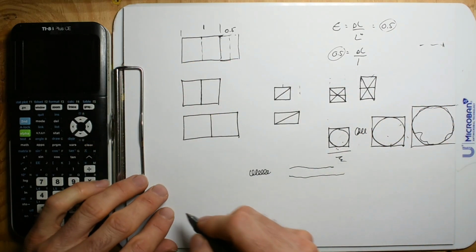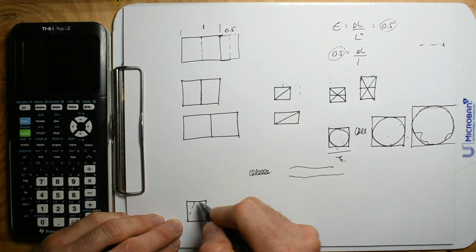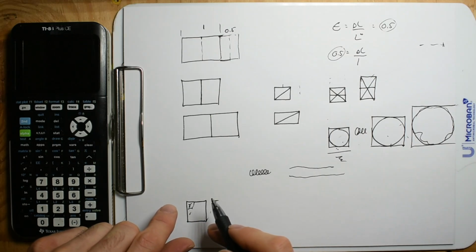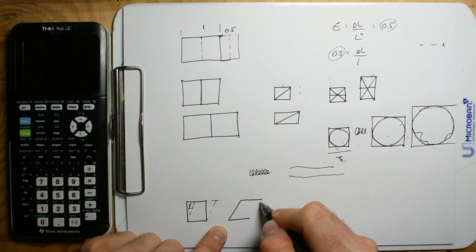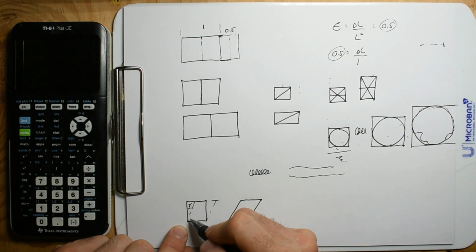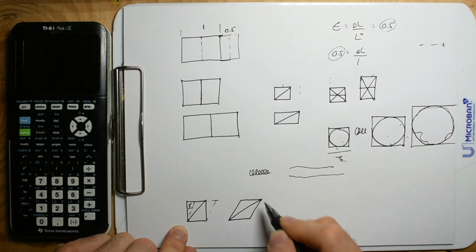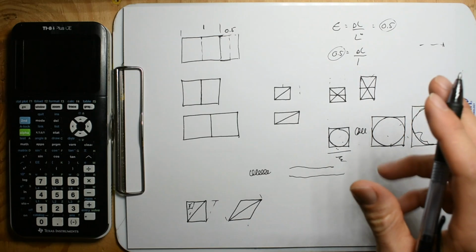And the same thing when we change angles. If this thing changes an angle to here, that's going to be that shear strain. And so now my new angle is going to be like this. What happens if I paint a diagonal line on? Well, that diagonal line is just going to be right there. Cool. And this diagonal line for sure changed in length. And so we're going to use that knowledge.